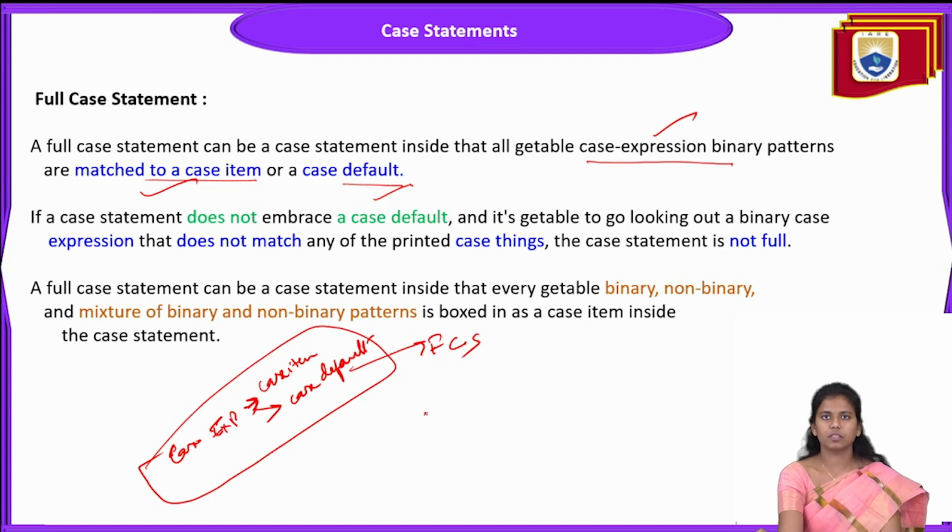Then if a case statement does not have a case default, and it is looking at a binary case expression and it does not match any listed case item, then that statement is not full. So we call it a full case statement only when the case expression matches a case item or case default.